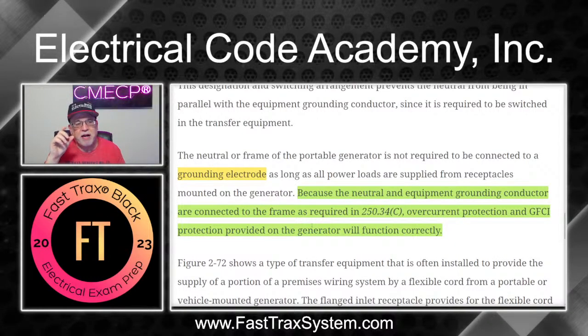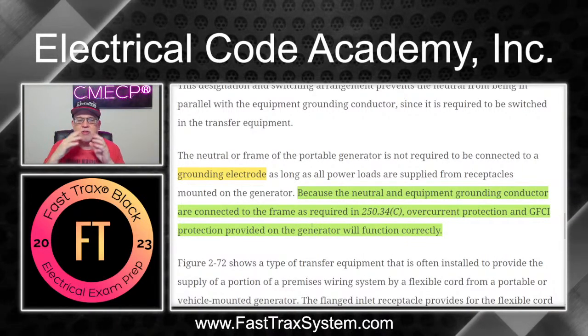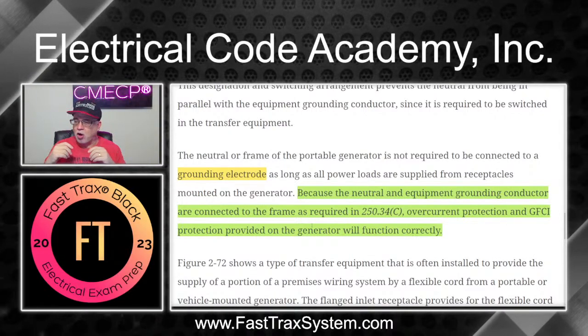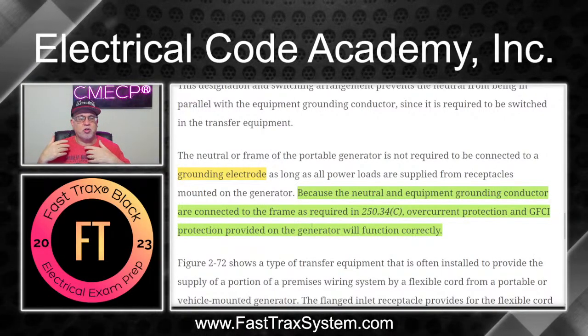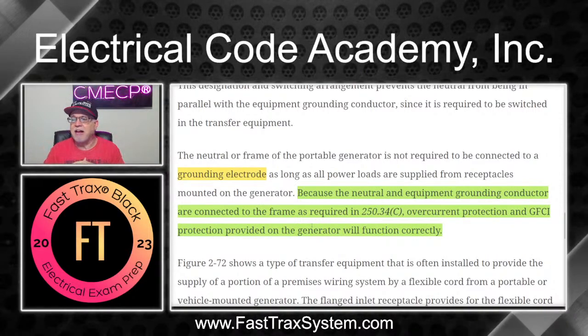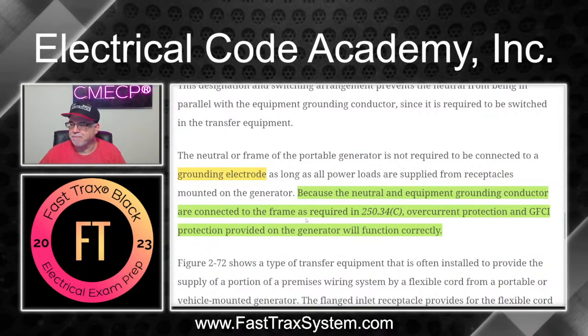The equipment ground terminals for the receptacle is intimate with the metal framing of the generator, which is intimate with the neutral point on the windings of the generator. If that's all done, and all the receptacles supplying the loads are cord and plug on the generator, or the equipment itself that's supplied by the generator is on the generator, then I do not have to have any electrodes. We've already established that, right? Okay.